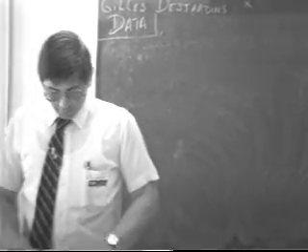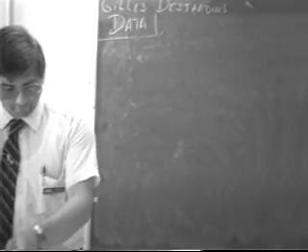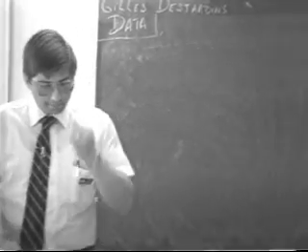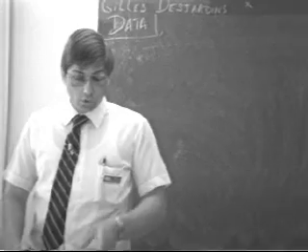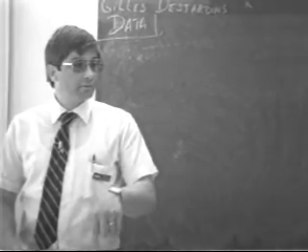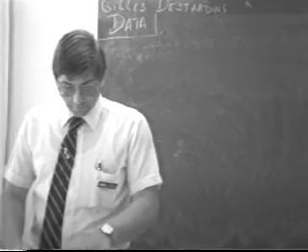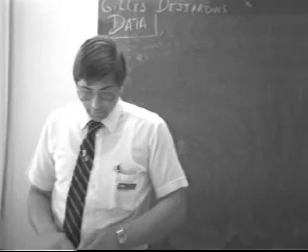If we did not want to test, we go to page 8. It reads the interrupt flag. Is a flag low? Yes or no? No, it will loop upon itself. If it is yes, there is an interrupt, so it has to enable the external interrupt.